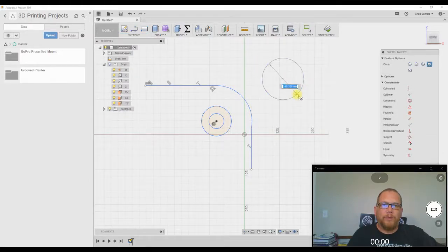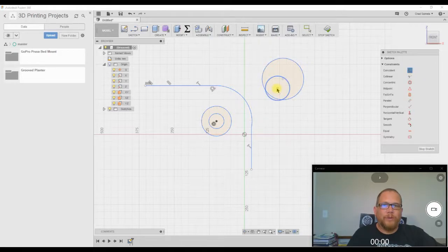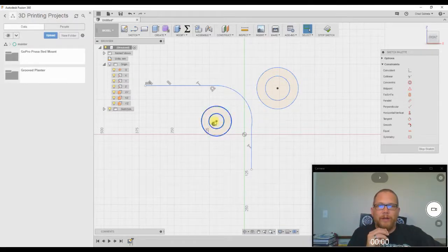If you've got the same coincident constraints, let's just say for real quick here, we'll put a circle and a circle, and let's say I use the coincident. It doesn't show it there until you hover over the points, and then it shows your coincident constraint. But when you do the concentric constraint, it will show that symbol on your sketch so that you can tell that they are concentric. If you click on it, it will show you. Anyway, it does show that symbol there, so you can see that it's concentric to stuff.